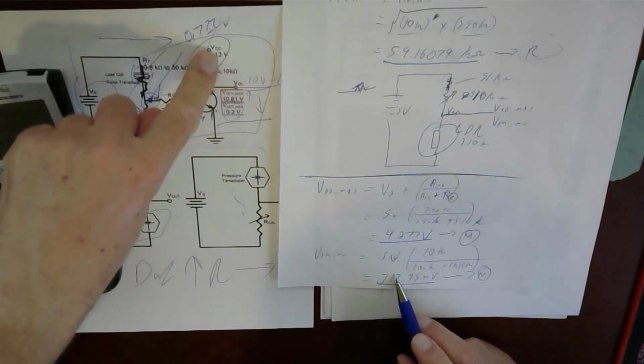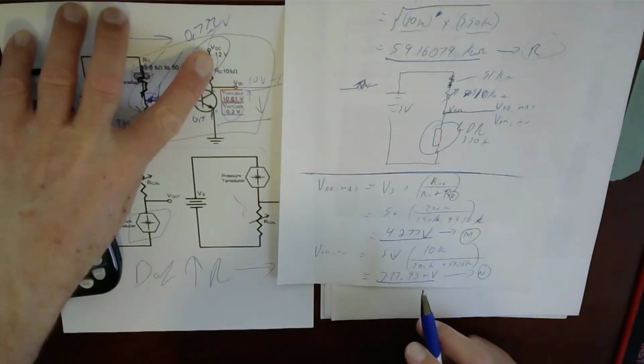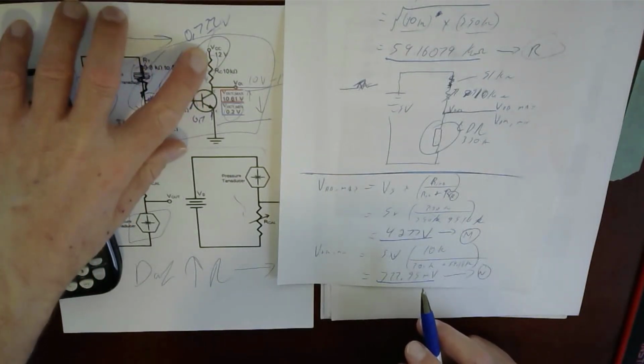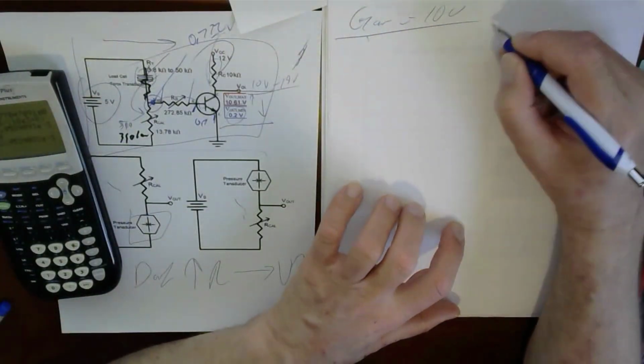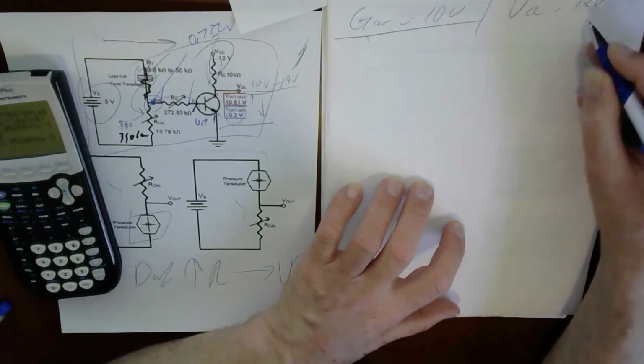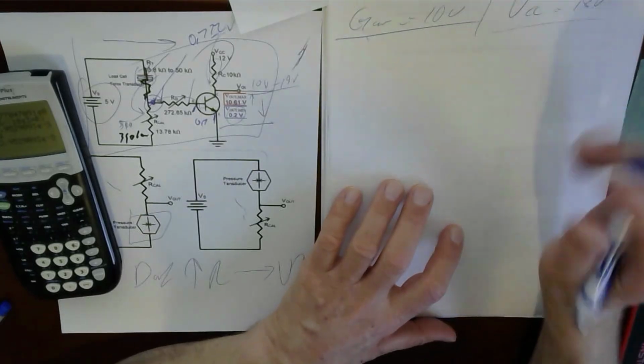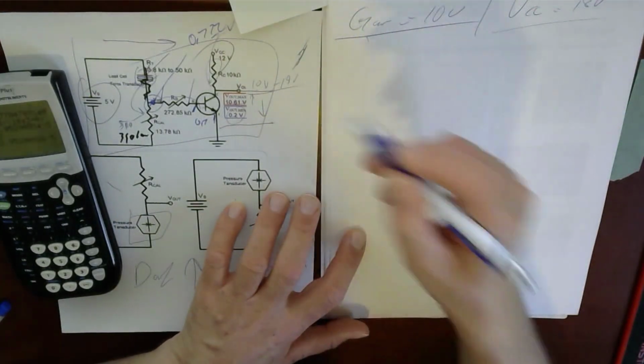So you know what? I'm just going to put an 18 there. I could put a 20 there, but I might even get 19 volts out. Let's find out. So I'm going to say VCC equals 18 volts. Now, if I get maybe 17 and a half or whatever, it's okay because the parameters say that the output is somewhere between 10 and 18.